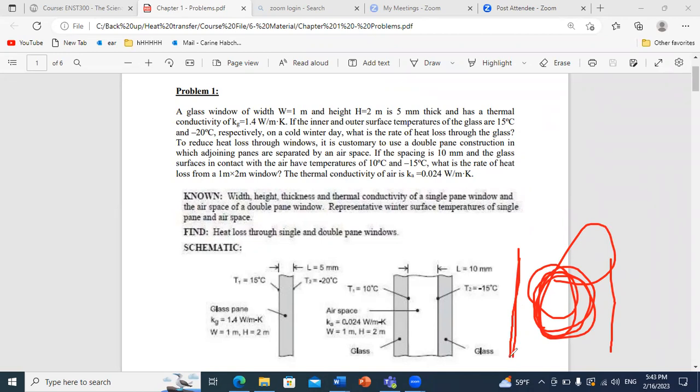That's why we can say here that this thickness should be optimized. And in the course material, we have seen a graph showing how with increased thickness, the conduction rate will be reduced, the convection rate will be increased. And then if we do the summation of heat transfer by conduction and convection, we'll get a graph like this nearly. So you can select an optimal thickness for which heat transfer is minimized.